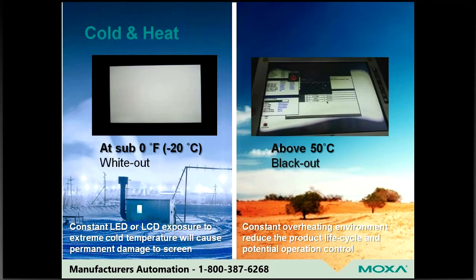Now, as we evaluate those challenges, the first is quite obvious, and that's temperature. The crystals in conventional HMI screens and panel PCs freeze at low temperatures and destroy the image and the actual panel display completely. And in hot zones, as we see all the time in the central USA, you can get a fusion of the panel screen. We have both displays here, actually tested at the Moxa facility.